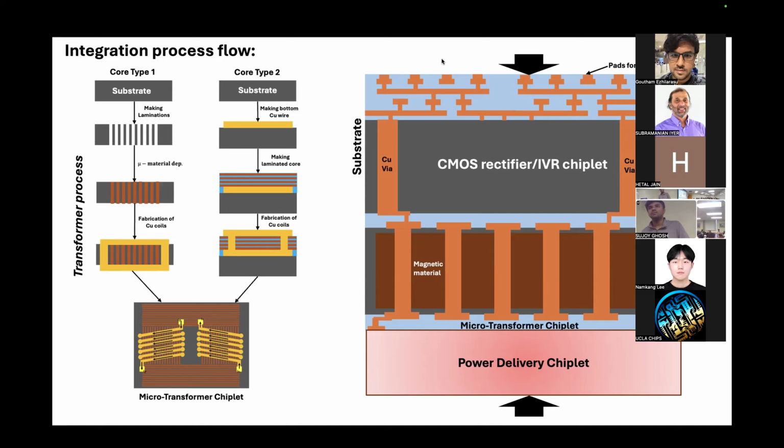But what if the material always needs to be 2 millimeters, regardless of the material? No, I'm not saying that, but we have to see. But the thicker it is, the better it is per unit area. No, that makes sense. That's also the reason why, remember the Global Foundries inductor we saw? The reason the inductance density is so bad is because it's just one thin layer. They have to integrate on the back end, otherwise the stress would be too high.